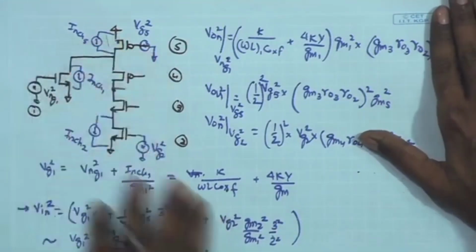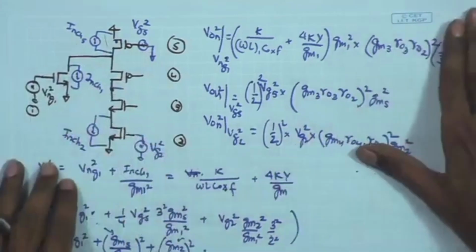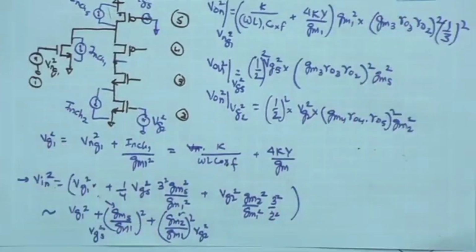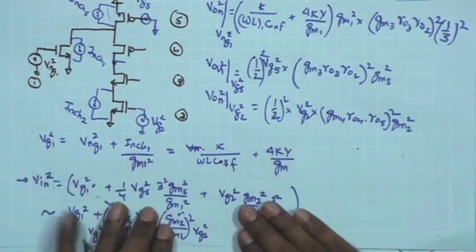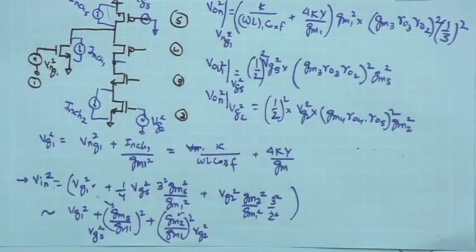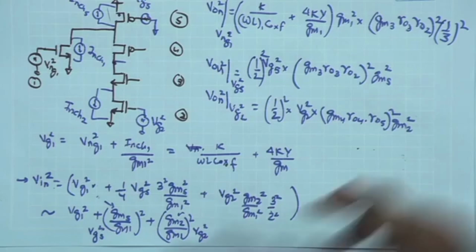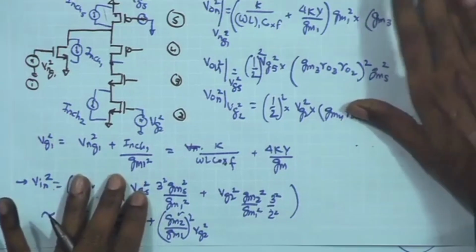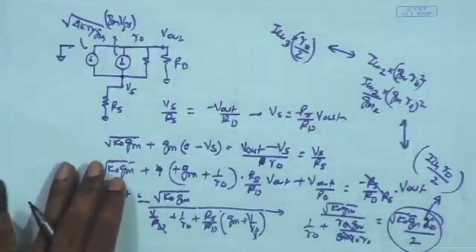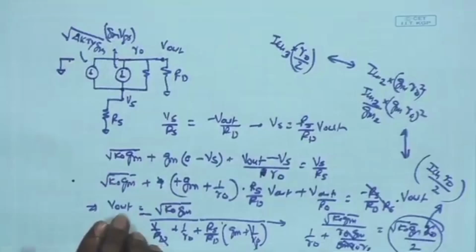Now once we have concluded that and we look back at this expression over here, we can again correlate it back to the analysis that we did with respect to frequency response and try to see how these two requirements are conflicting: requirement of lower noise and requirement of higher bandwidth and good gain, if at all there is any conflict. So before we go further, any discussion on whatever we did with respect to the noise contribution of cascode devices?